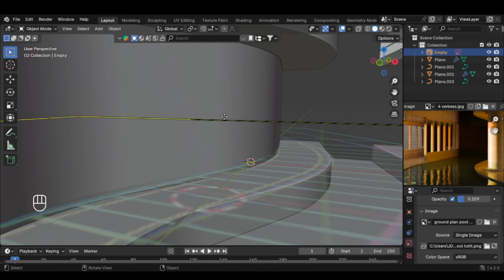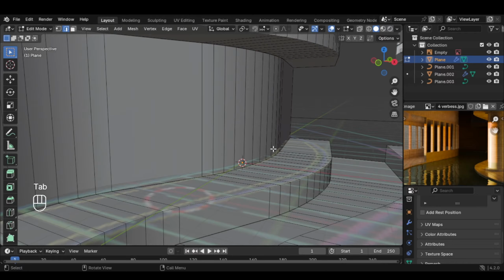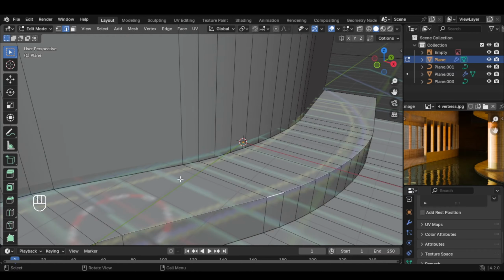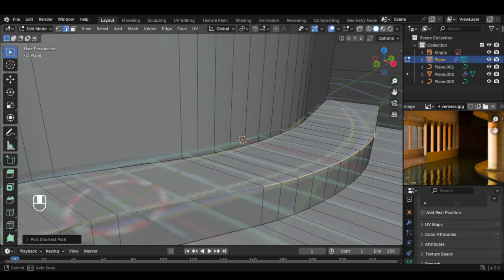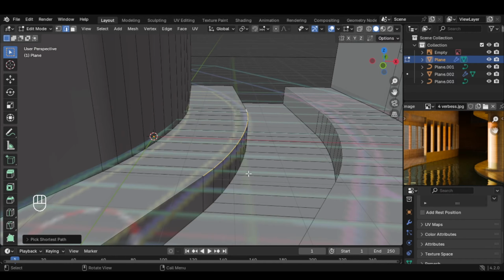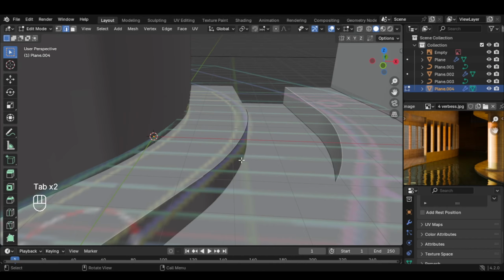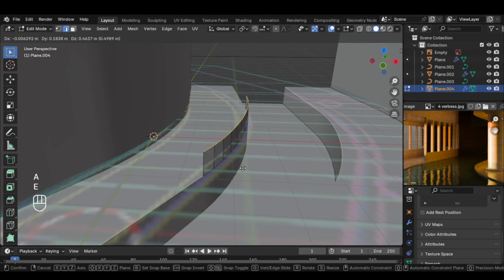Let's create this one here, this object. So we're gonna select our building and press edit mode, tab, and what we're gonna do is select these edges here by pressing one edge and go to your edge mode. Select this one edge, hold both keys, Ctrl and Shift, and select the other one, and then just press P to separate by selection and select this edge.